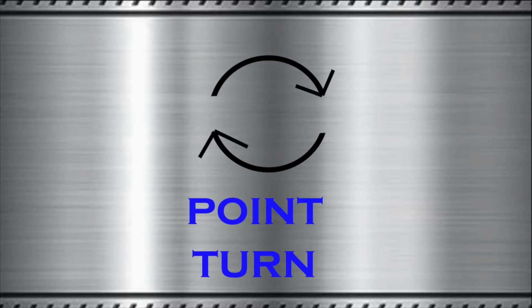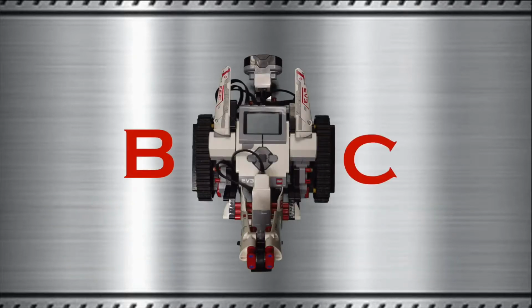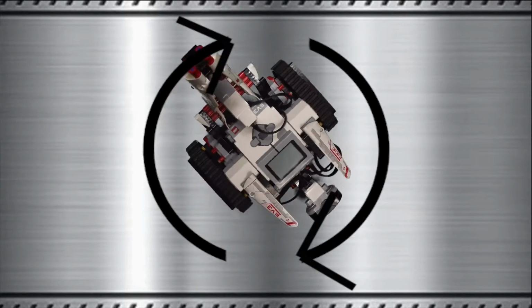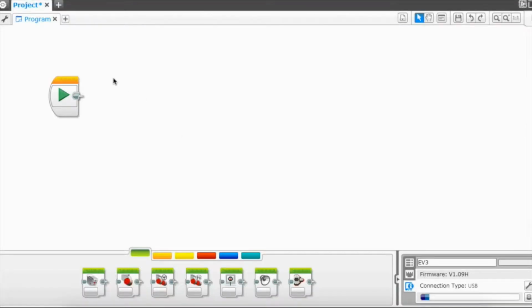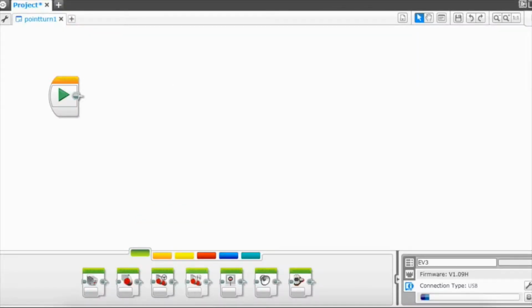Now let us create a point turn. A point turn is different from a swing turn as it uses both the B and C motors at the same time, so that your robot can turn on the spot. So let's begin a new program for the new move. Let's call this one Point Turn 1. And, just like before, place a tank motor block next to your start point.